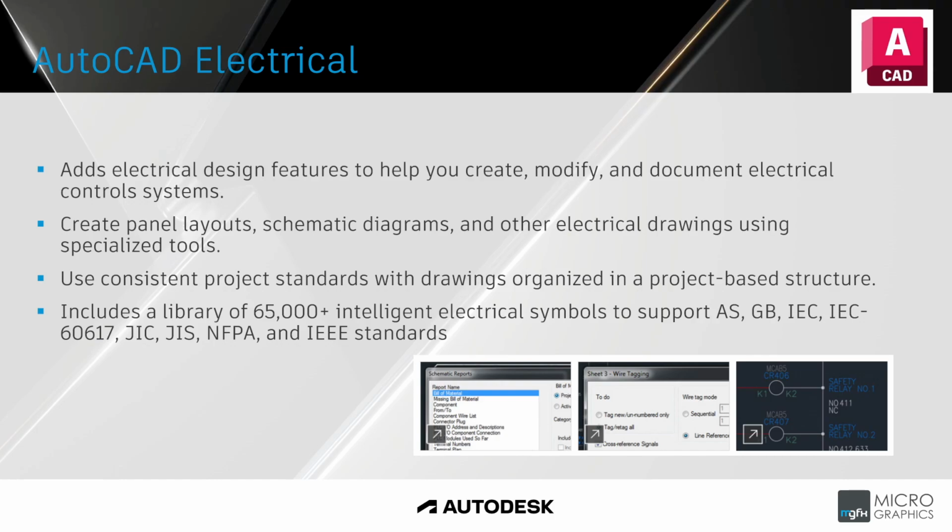AutoCAD Electrical. This is a great way to create electrical drawings. Normally what guys do is put all their different title blocks on one DWG, say 16, 20, 25, 30, and start drawing the electrical schematic, one line diagrams, and when you fill up the page, they go to the next page, the next page, the next page. Now what AutoCAD Electrical does is control line types like from, to, destination, source. So you don't ever have to remember, okay, this wire needs to go to drawing 6 or 5. Where does it come out? Is it a column? Is it a grid identification of where it comes out? AutoCAD Electrical will control that for you.